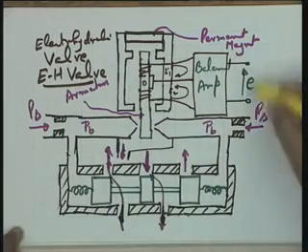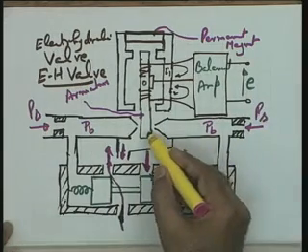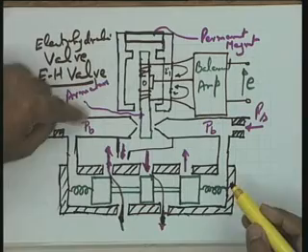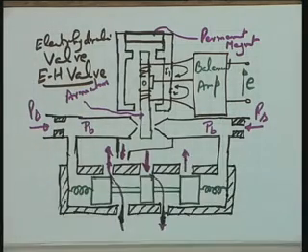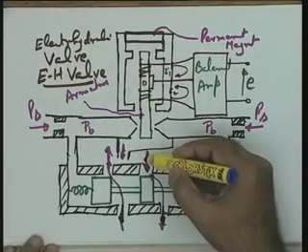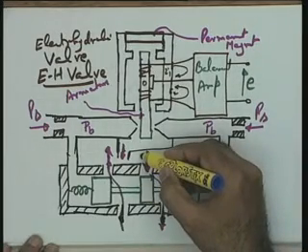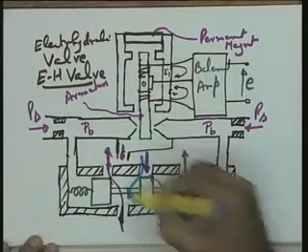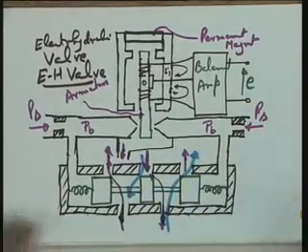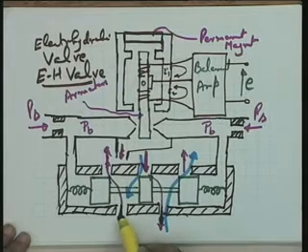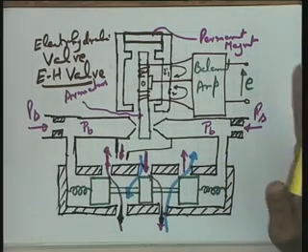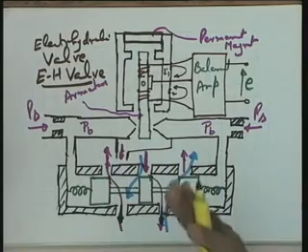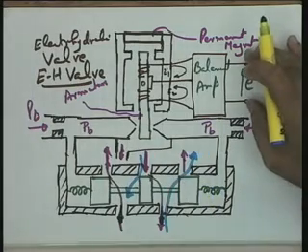So now you assume that the polarity of E changes. In that particular case, this flapper goes this way, and hence this pressure increases, and hence this moves this way. And now if this moves in the opposite way, let me use this color. In that particular case, you can just see this pressure is available here, and the drain is like this. If this moves in the opposite way, this particular port gets connected to the high pressure line, and this particular port is connected to the low pressure line. So this is the interface between the hydraulic actuator, the power cylinder, and the electronic amplifier.